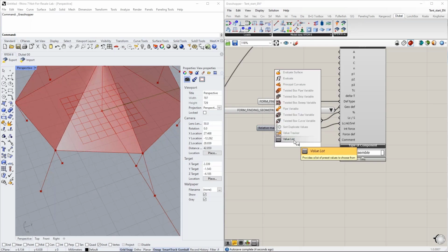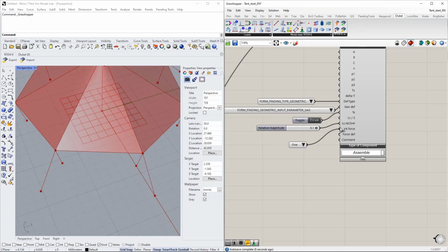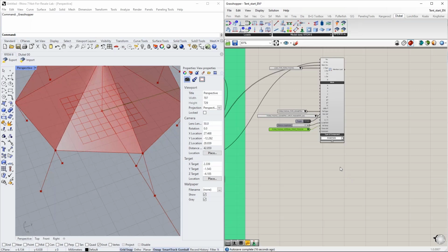And it should be a tension related form finding load. We also have form finding for compression. This is also possible, form finding for compression or structures under compression. In this case, I will, however, link it to my tension forces. Okay, so the first load is defined.